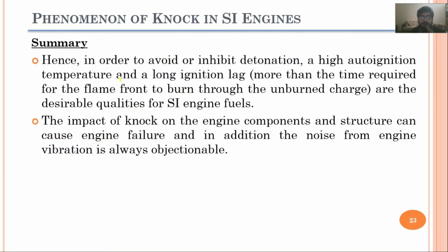So in order to avoid detonation, or knocking, a high auto ignition temperature of the fuel is desirable. High auto ignition temperature means that the fuel should have a longer ignition lag, meaning it requires more time for the flame front to burn through the unburned fuel air mixture.